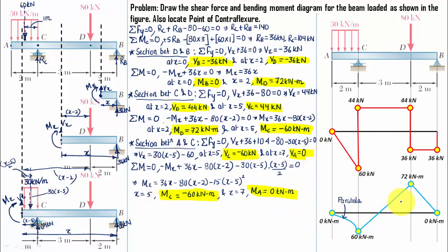Now guys, you can clearly see the bending moment over here was positive and the bending moment over here was negative, and this is exactly the point where the bending moment has changed its sign. This is positive and hence represents sagging, and this is negative and hence represents hogging. What essentially I'm trying to say, if you try to make a point, if you try to just do this, let me join this. Something of this sort, and when the beam bends it would be something of this sort. This is where sagging happens, positive bending moment, and this is where hogging happens, a negative bending moment.